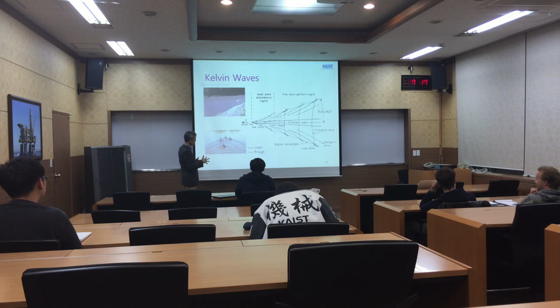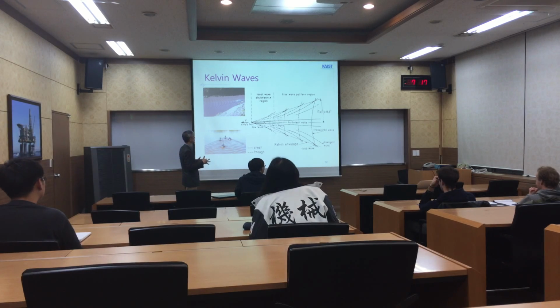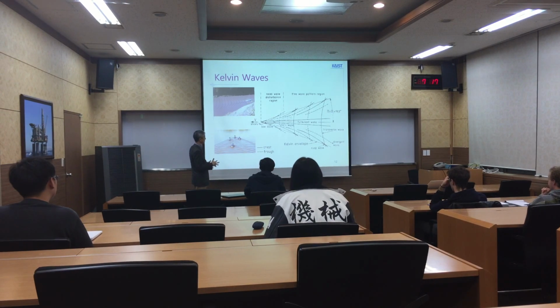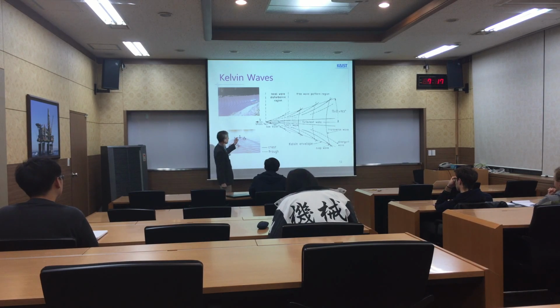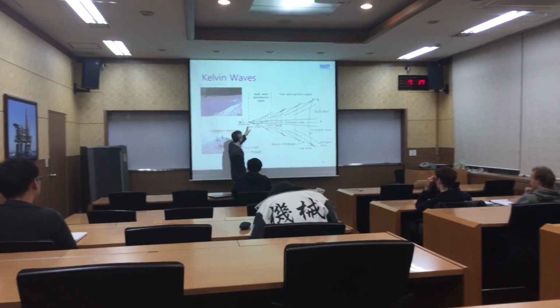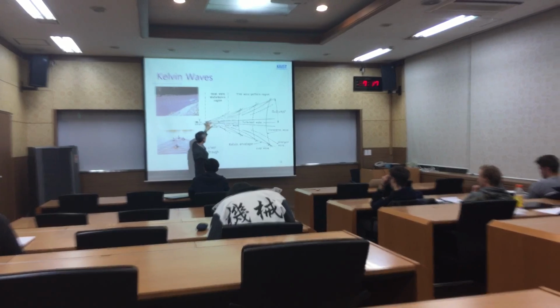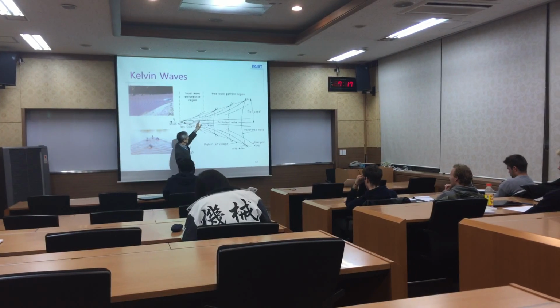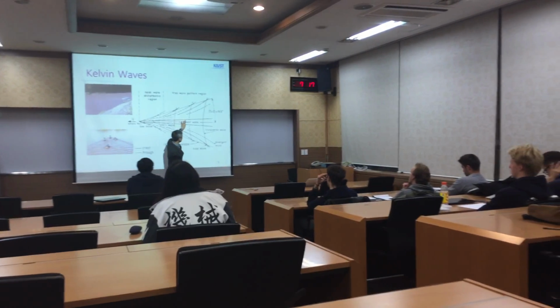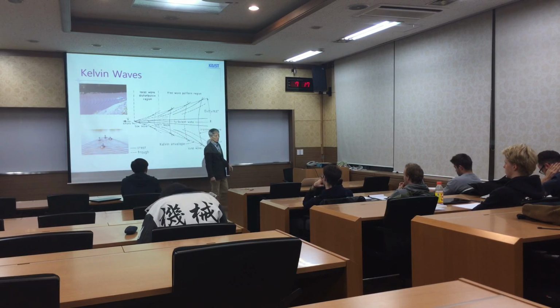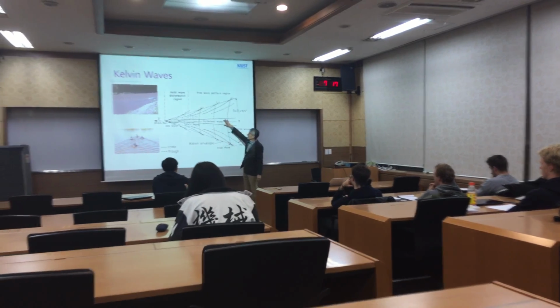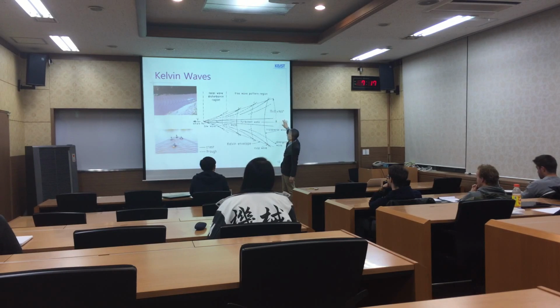They are also creating waves. So this is wave making resistance. There are details, different waves coming from bow and stern, and also there is a turbulent wake zone. This is pretty stable and long staying.